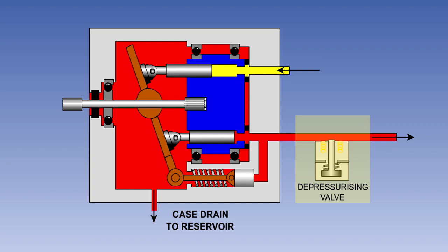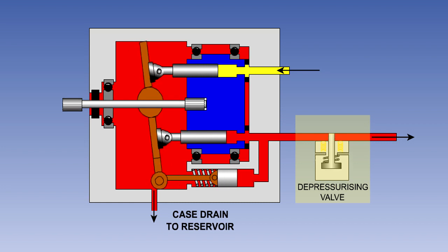On some pumps, a solenoid-operated depressurizing valve, offload valve, can be used to block delivery to the system and to offload the pump. System pressure is maintained and the pump output falls to below 1000 psi, allowing case drain oil to circulate, lubricating and cooling the pump. This valve is useful in the event of a leak in that part of the system supplied solely by its pump. The solenoid is energized to offload the pump, so in the event of solenoid failure, the pump will continue to operate.